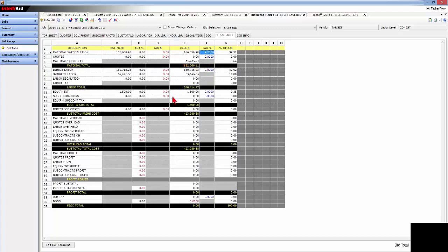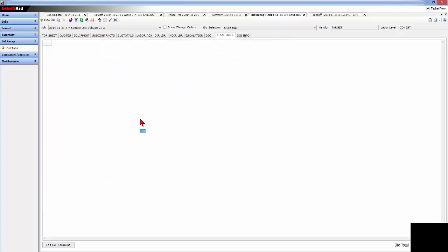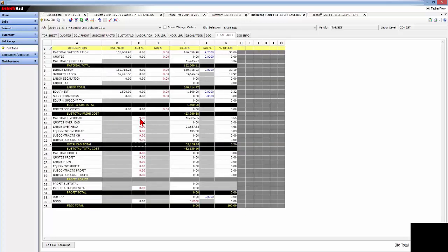Now, the material totaled, your labor totaled, equipment and subcontractors, we didn't put any direct job cost. And line number 16 is your prime cost at $423,980. Your accountant would usually let you know what your overhead is for the company operations, which would be added to the job, totaling $462,000, which is your true cost to do this job before any fee or profit.